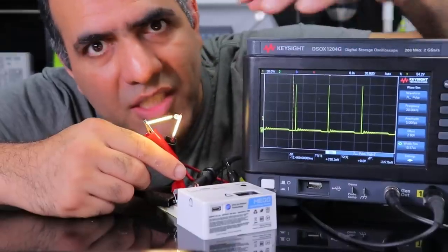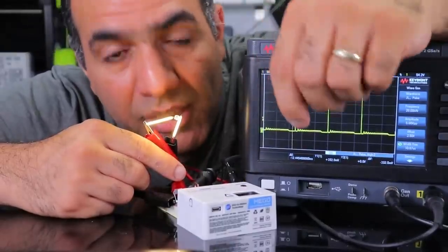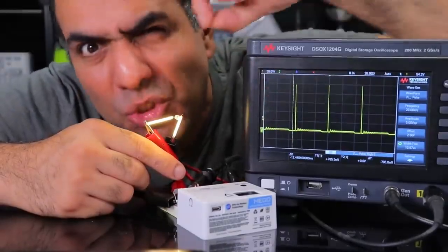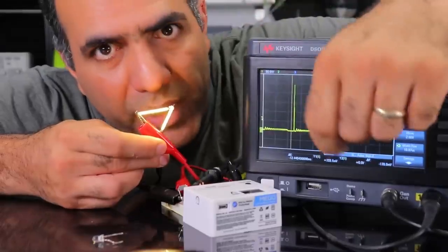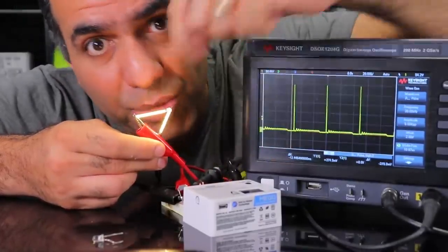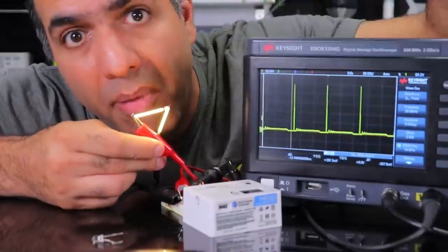Remember, although you can send a certain maximum current continuously through the LED, you can send maybe 10 times that through the LED at short intervals. As long as the component doesn't heat up above its burning threshold, you can increase the current through it to much higher than the maximum continuous levels, say by pulsing the current.